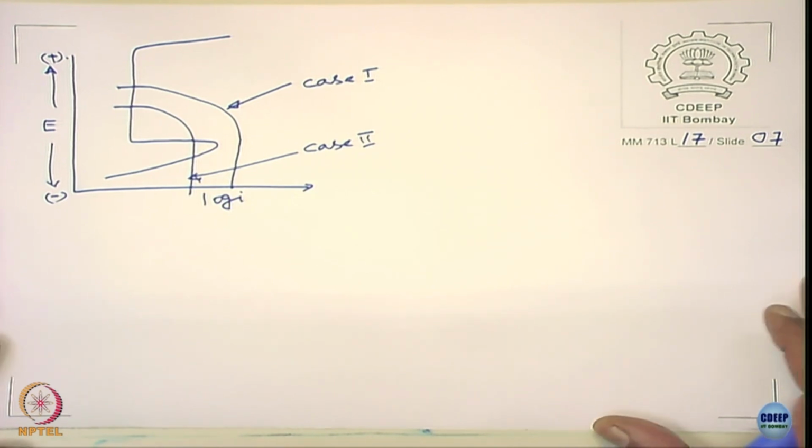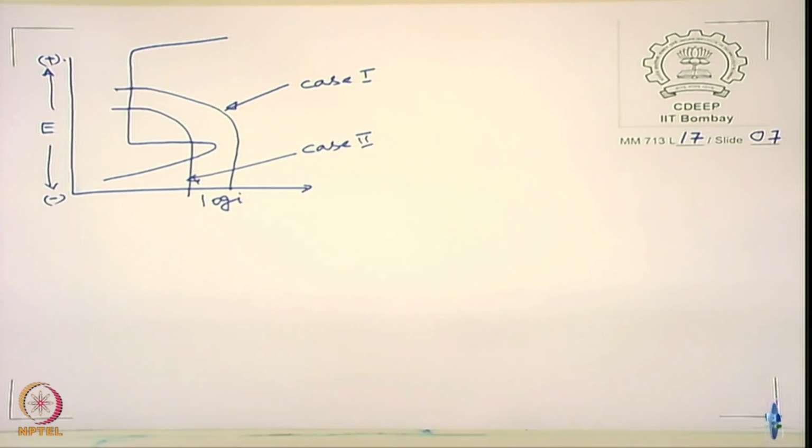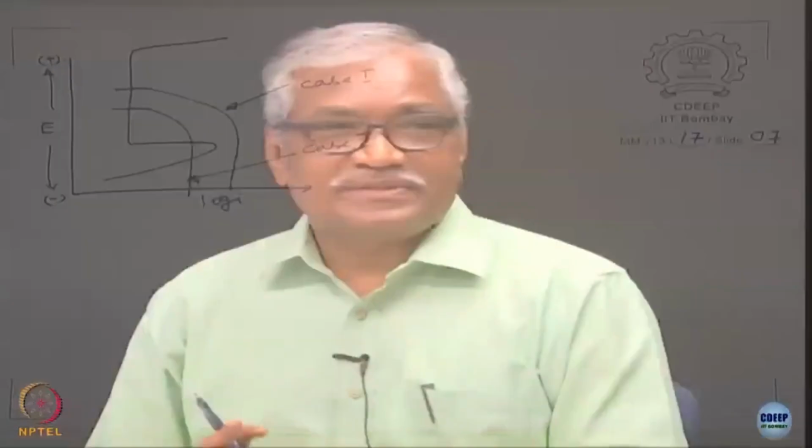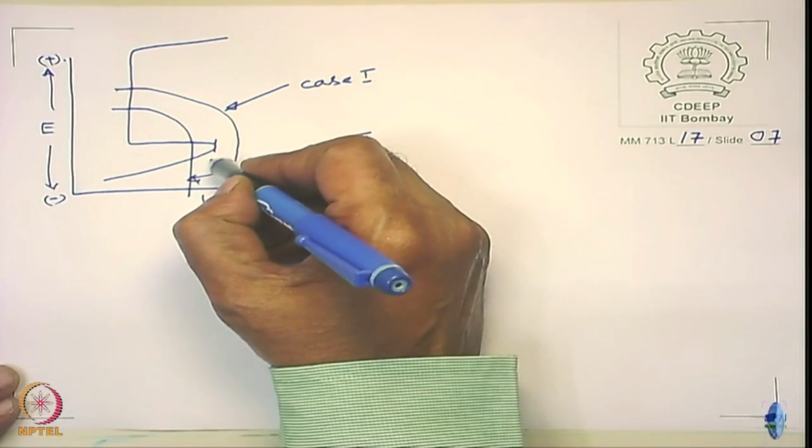So coming back to the point, on a single metal surface, in one place you have more oxygen content, in another place less oxygen content. The place having less oxygen content would not tend to become passive. The place having high oxygen content will tend to become passive, because of what? Because you need a certain current density to cross the I critical value. You need to do that.